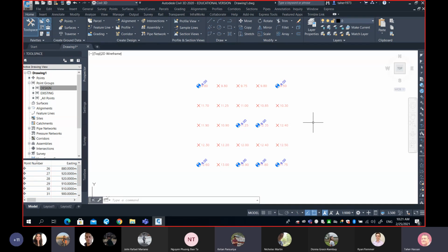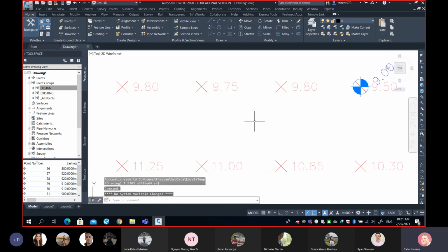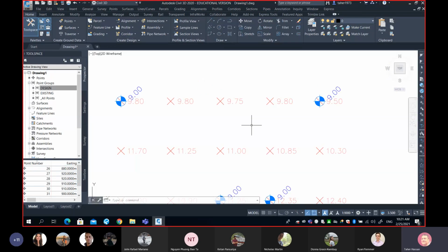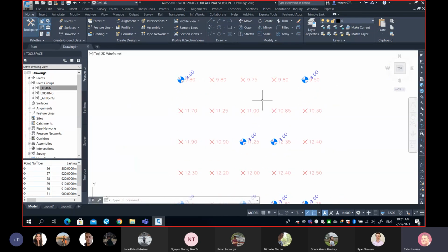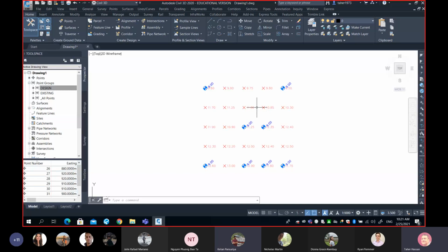Find depth of cut and fill. The cut and fill cannot be estimated right now because we do not work with discrete points. If you guys remember, these are discrete points. So, for example, right now, do we know the elevation here of my cursor? Do we? Do you know what's the secret to get a continuous representation of the ground? Create a surface. Thank you, sir.